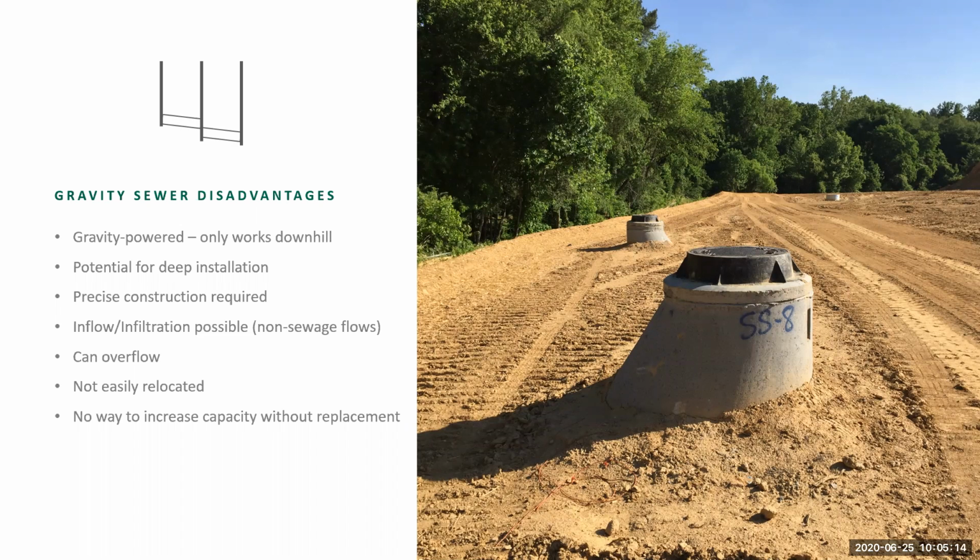They're also not very easily relocated. I mentioned the specific slopes that they're designed for. So if there's a relocation that adds length, then meeting that minimum slope is going to be difficult. And there's no way to increase capacity without replacement. Now, there is one caveat to that I'll touch on in a bit, but for the sake of this discussion, replacement is generally the only way to increase capacity.